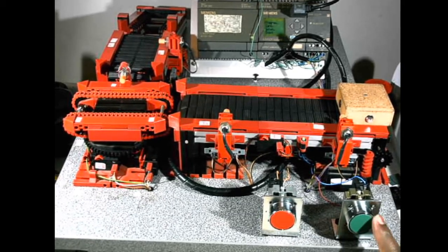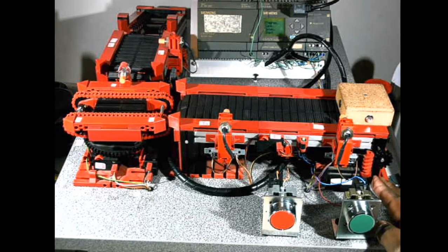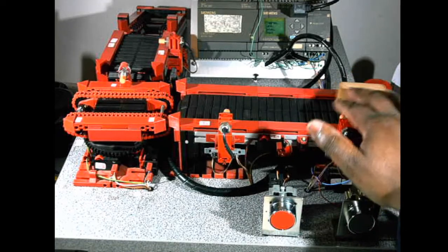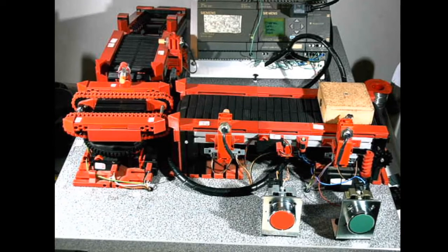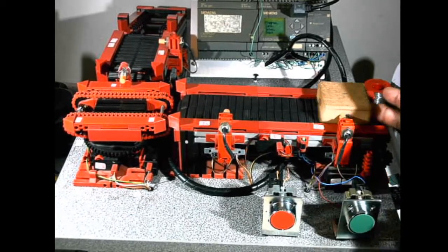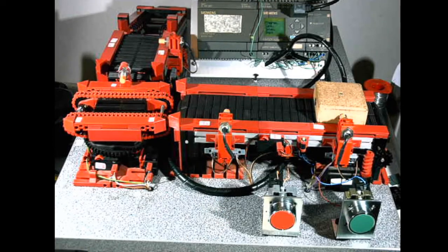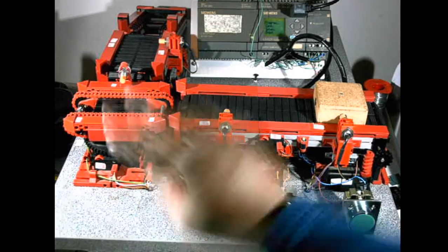So this input here is input 9, and the labeling on the motor for this direction is Q5 and Q6 according to the labeling. The sensor here, it's I6, that one, it's I5, the next one, it's I3, and we have I1 and I2 there. So this one is I1, the other one is I2.